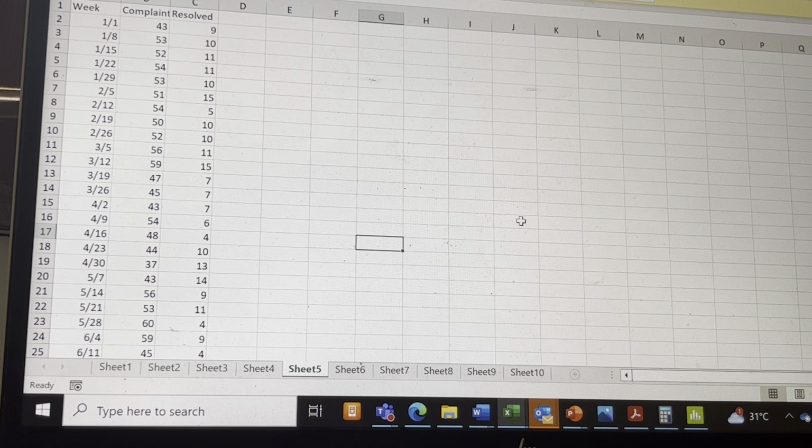So can you tell me, is it a data on defect or defectives? Defectives, because it is not about defects, it is about those incidences which are reported, how many of them you could resolve. Now make a note. If you have a control chart on defectives, you can do P chart or NP chart. P chart when subgroup size is constant.